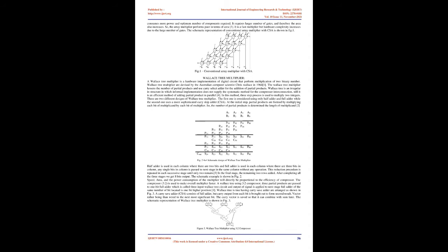In a serial multiplier, each bit of the multiplier is used for evaluating the partial product, whereas in a parallel multiplier, partial products from each bit of the multiplier are computed in parallel. The main parameter that determines the performance of the parallel multiplier is the number of partial products that are to be added. In a parallel multiplier, the speed is compromised to achieve better performance in terms of area and consumption. Depending upon the type of application, the parallel or the serial multiplier can be used.